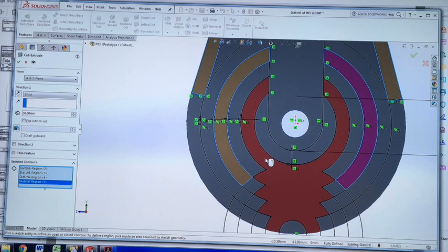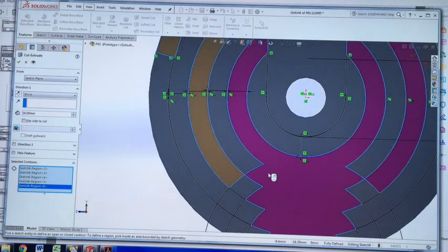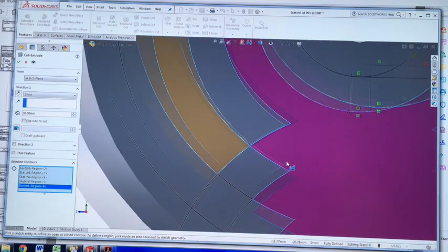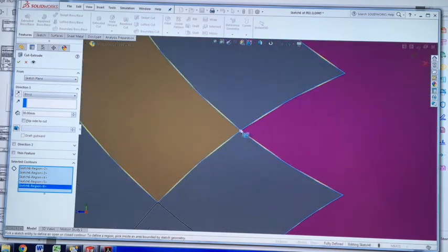Now there are limitations to that, because where I'm cutting away this space, when I select these two, and you guys may have encountered this so far with errors popping up, this would create what's called zero thickness geometry.